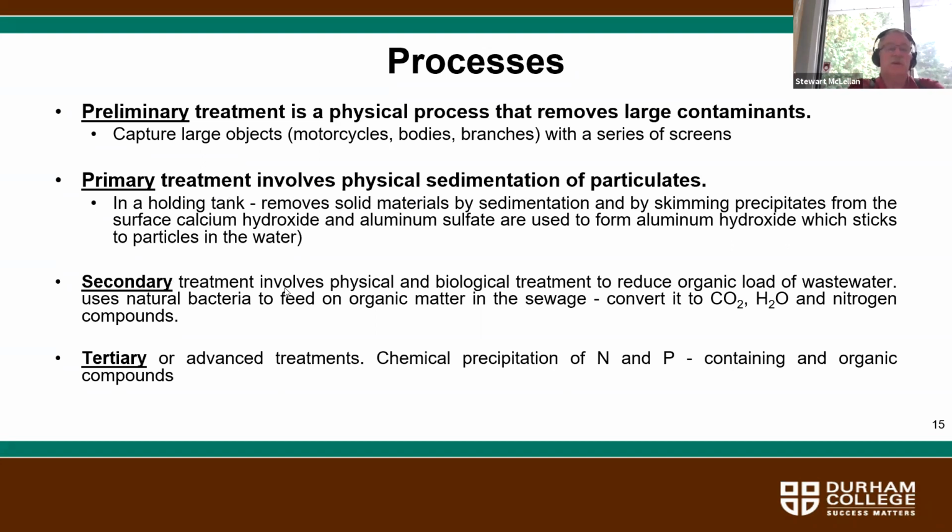Secondary treatment involves physical and biological treatment to reduce the organic load of wastewater. It uses natural bacteria to feed on organic matter in the sewage and convert it to carbon dioxide, water, and nitrogen compounds. We talked briefly about BOD, the biological oxygen demand.